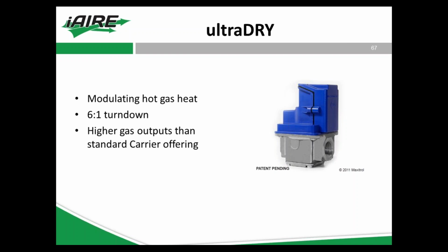So if you're familiar with what Carrier offers from a heat capacity standpoint, generally you would find that they wouldn't be suitable for Chicagoland design winter conditions, so going from that -10 back up to 70 degrees or even higher in a lot of situations. So they do offer the ability for a higher capacity gas heat exchanger that allows us to use these DOAS units in cold climates like Chicago.